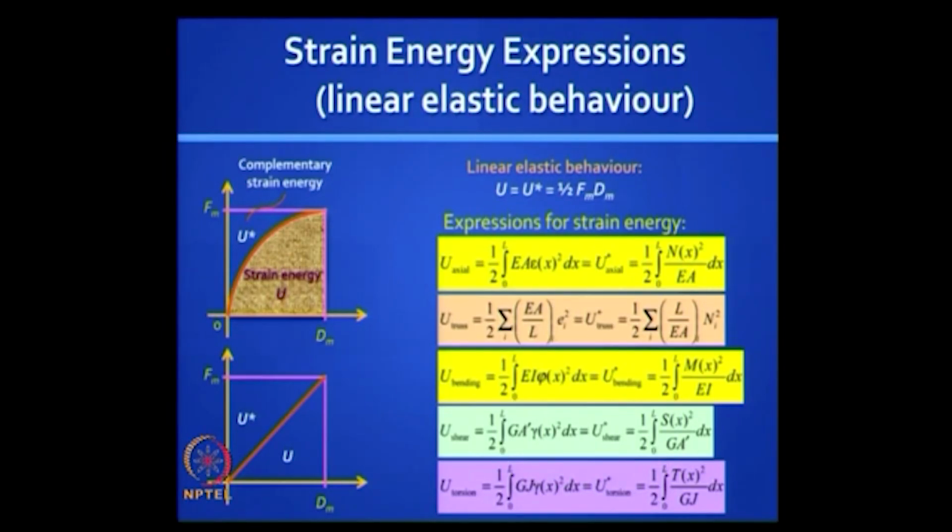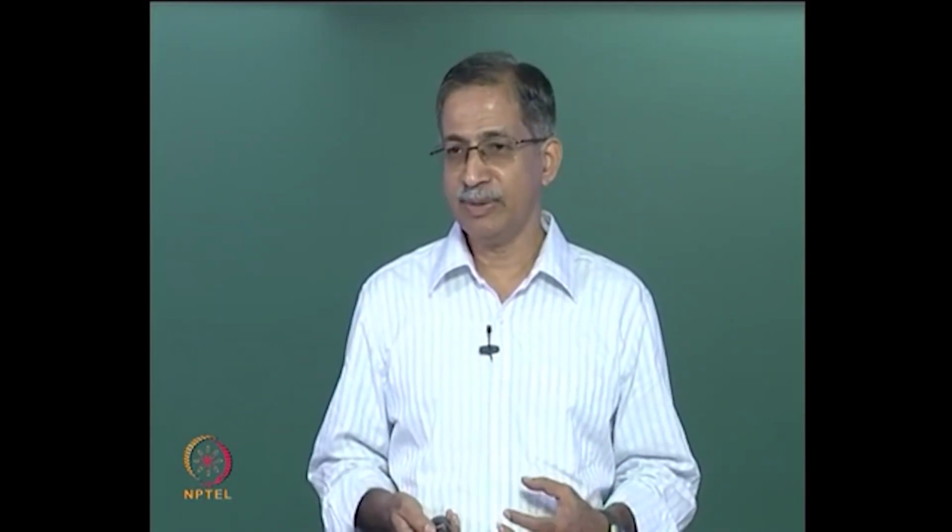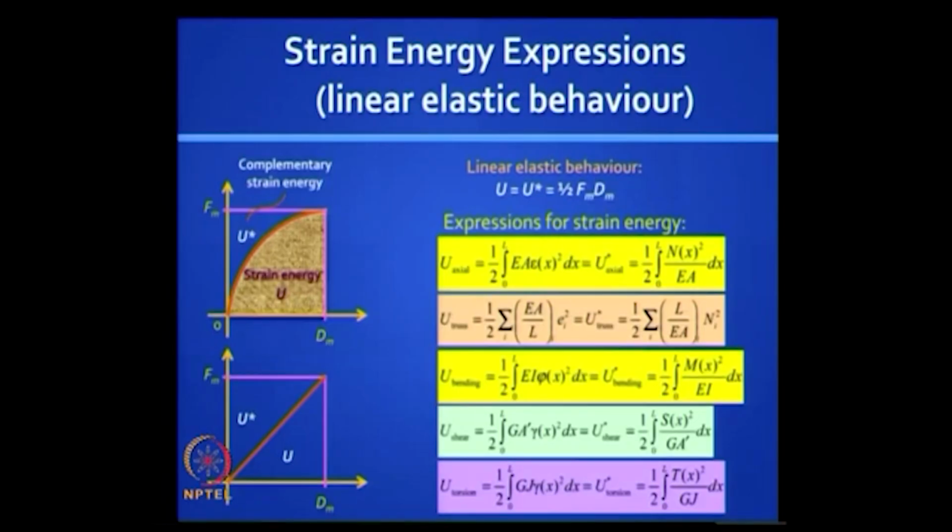For shear rigidity you have GA dash, and that gives us the shear strain energy, and GJ for a prismatic circular section, J is the polar moment of inertia, G is the shear modulus. For non-prismatic sections and for non-circular sections you do not have a case of pure torsion, you have warping coming into place, you have some distortion coming into place.